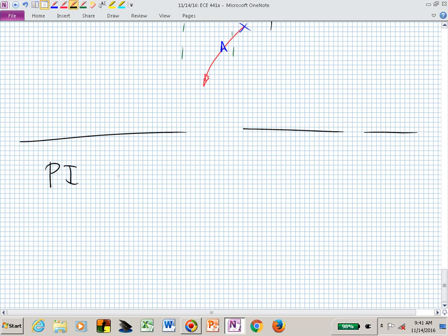If we just did a PI controller, this gives us now a G sub C, which is K sub P plus K sub I over S. And if we put that over a common denominator, we have a 0 and a pole. But now the pole is locked at the origin, and the flexibility that we have is adjusting the zero's location. So now we flipped the orientation of our pole-zero combination. Now we have the pole to the right of our 0. In the phase lead, we had our 0 to the right of our pole.